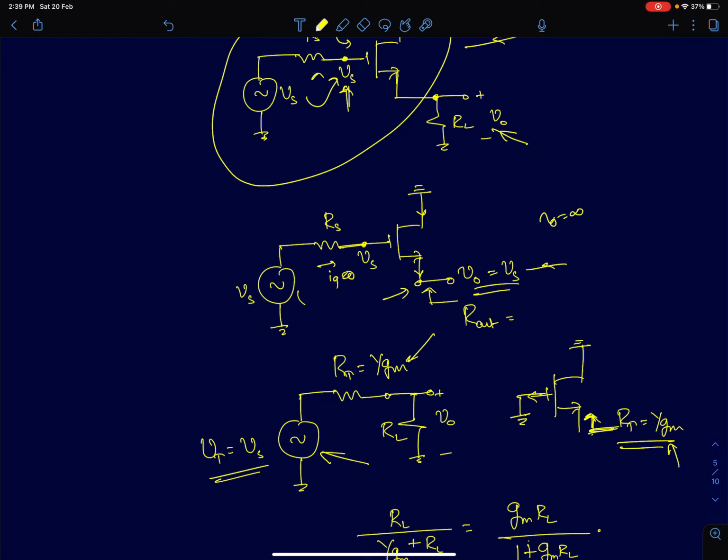Now if you see, the load resistance was previously seeing a source resistance of value Rs. But now after introducing this amplifier, it looks like a completely different source. The load now sees the same source voltage but with a very different source resistance. The source resistance is now equal to 1 by Gm, which is now under the designer's control. This 1 by Gm, Gm can be manipulated by choosing an appropriate drain current and W by L ratios. Now it's within the control of the designer.